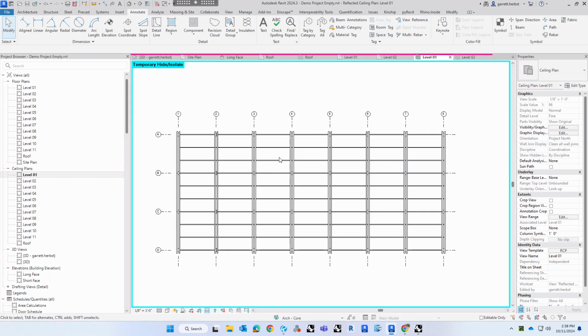So right now in this configuration, your primary beams are running up and down, your purlins are running this way. The reason why your purlins are running east-west is because your CLT is actually sitting on top of them in this direction. So they're being cantilevered, spanning between these two purlins. If you were to do a one-way slab, depending on how you want your CLT to be oriented, then they would actually...